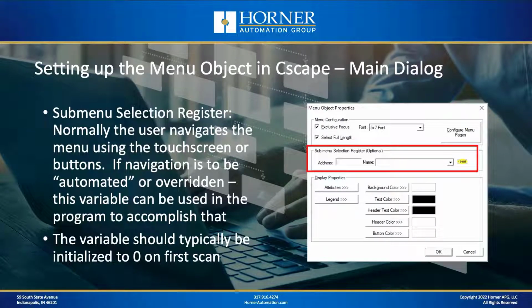Now that's an advanced feature. I wouldn't necessarily recommend it for most applications. As a matter of fact, the application I'm showing you, which is going to be pretty typical in a lot of ways, doesn't utilize that register at all. Now if you do utilize that register, remember you're going to want to initialize it to a value of 0 so that when the user starts off at the menu, they're starting off at the highest level. Whereas if you leave it with a non-zero value, they're going to start out somewhere in the depths of the system menu, or of their custom menu that they've created. So again, most cases you don't need to utilize that feature, but it's there as an advanced feature.